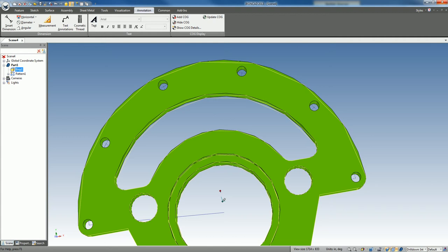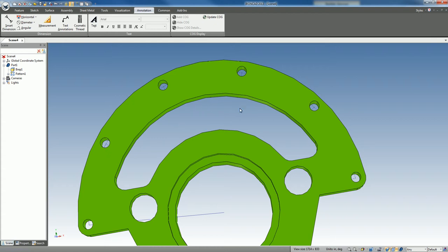At this stage, there's no real way to make a change back to where you were before. For example, maybe this particular stage of the design wanted to be one cutout, but what if it comes back and says, oh no, we actually need to make that 2 or 3 individual cutout spaces? Well, if you look at the shape, it's still one B-rep. There are no cutouts here anymore.